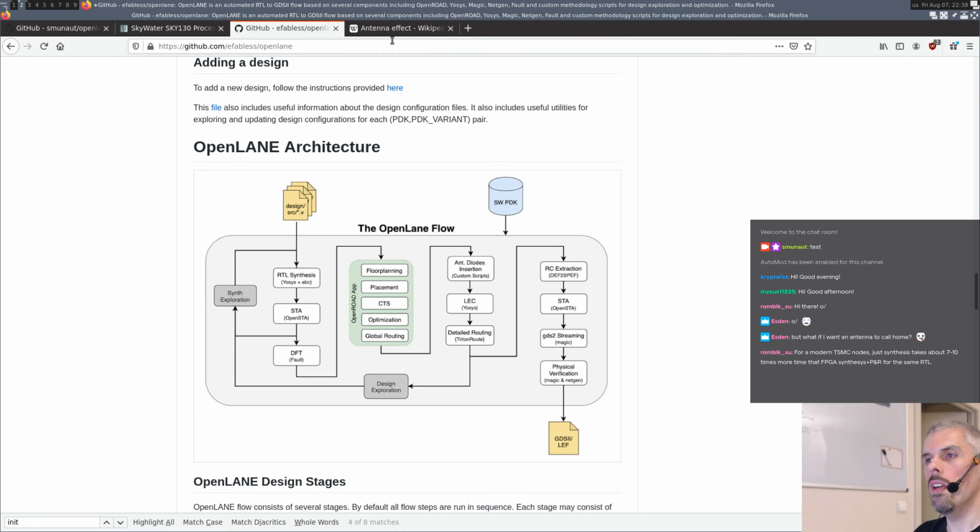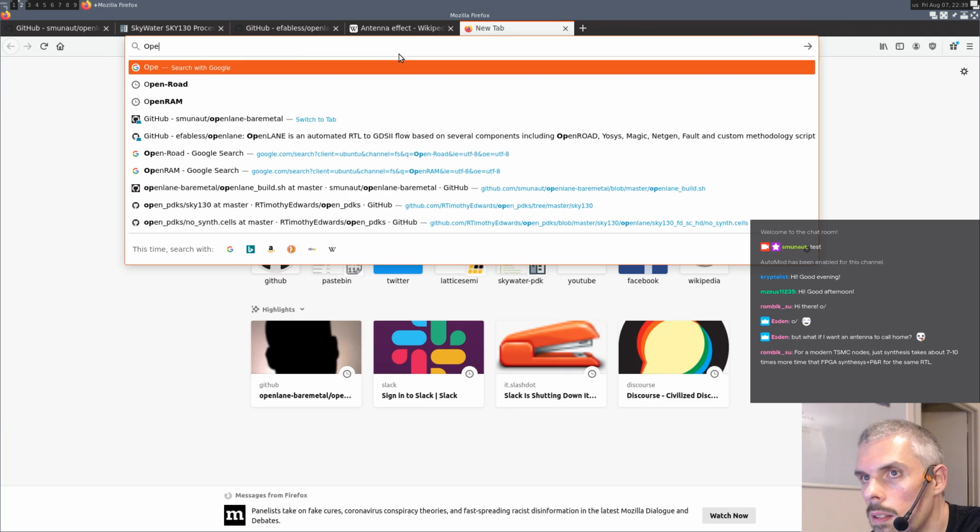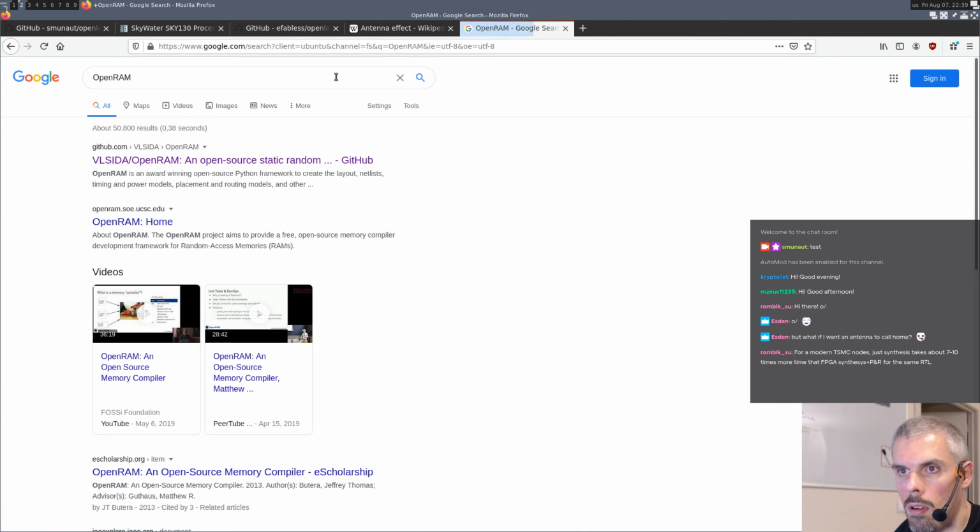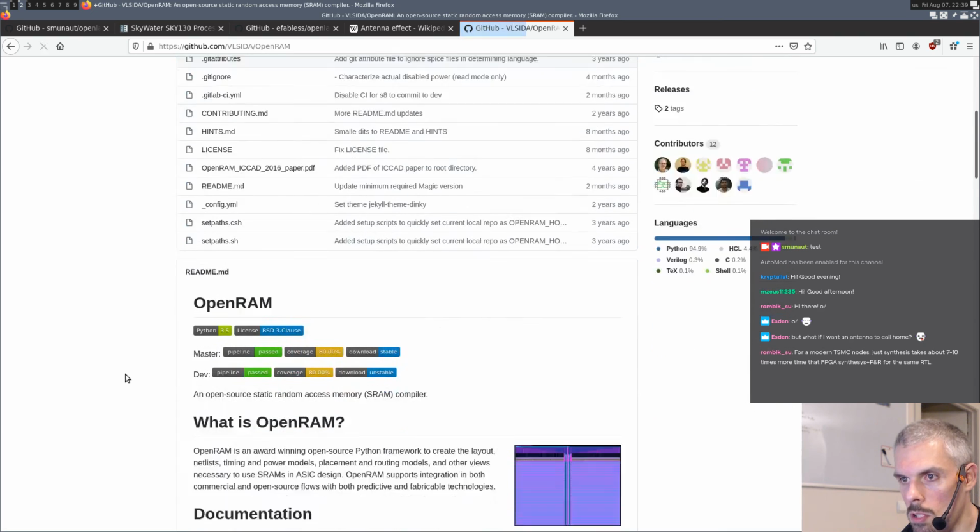First, you can use a bit of SRAM, like a memory macro on the ASIC. And typically on an FPGA, if you look at how the register file would be implemented, it would use either a small distributed RAM, or like on the ICE40 or the ECP5, you're going to find a block RAM used for the register file. And so here we could use an OpenRAM macro and implement the register file that way, right?